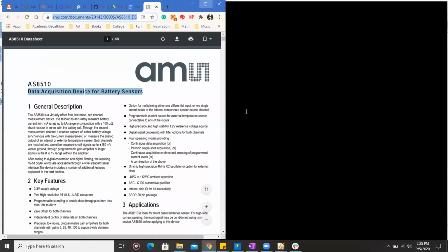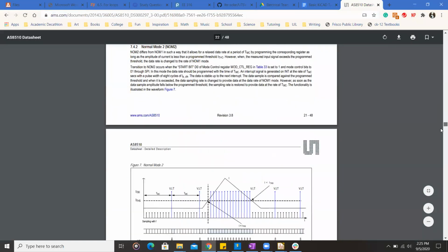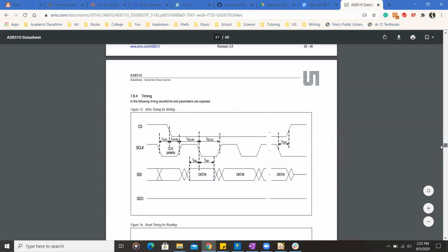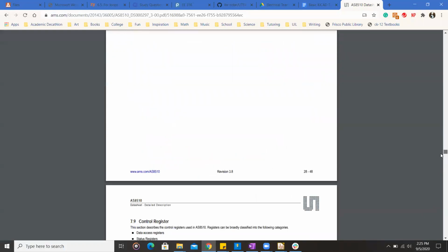Now we have to go back to the data sheet again, and we want to find out its dimensions. This part is a lot more crucial than the schematic part. When you're creating a symbol, you want to pay attention that you're assigning the right pin numbers to the right pins, because if you mix it up and then lay out the trace that way, then you're connecting it to the wrong pin. So make sure you double check that whenever you're working on that.